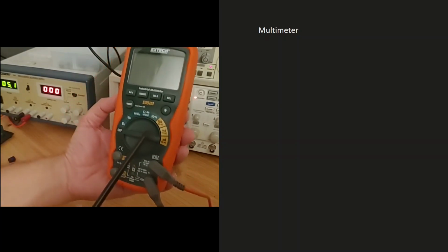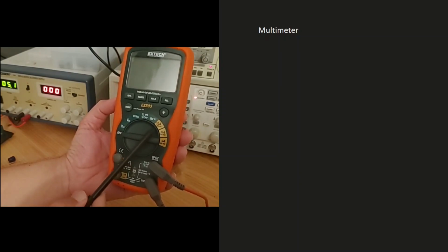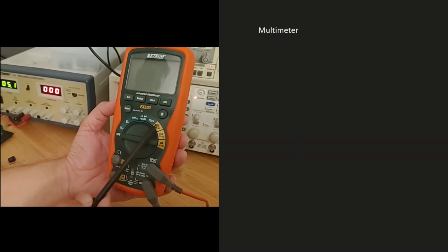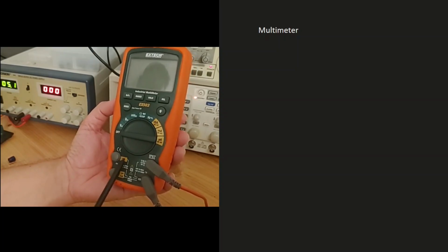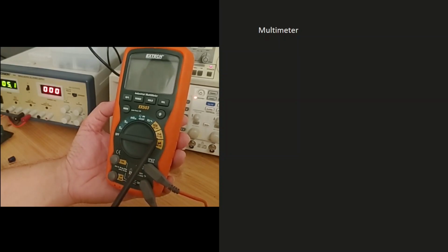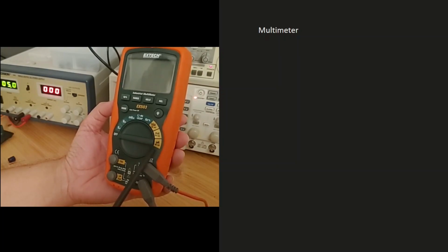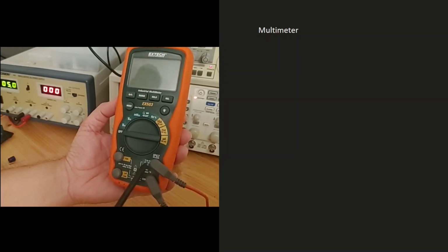But when we are measuring current, so we have in this multimeter, I have these three different options. The first one is 10 ampere. So if I want to measure a large amount of current, then I will use this setting, 10 ampere. And when I'm measuring 10 ampere, then I will have to bring the red probe to this location, which says 10 ampere. On the other hand, if I'm measuring a small amount of current, for example, milliamperes or microamperes, then I will use this location for the red probe.